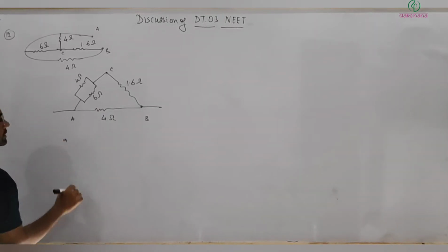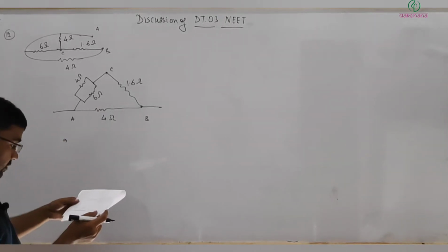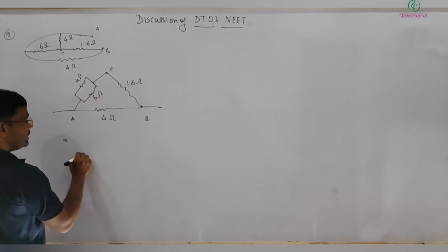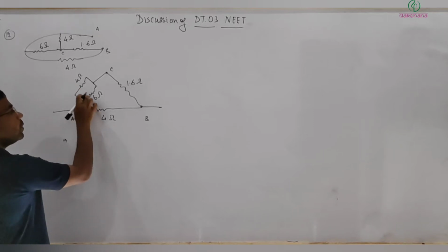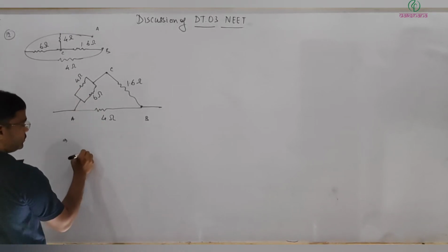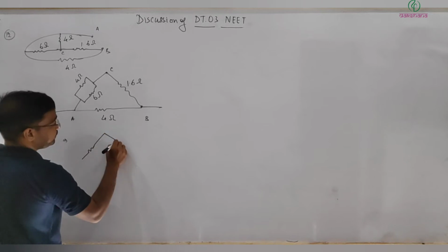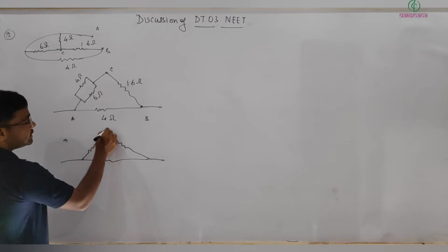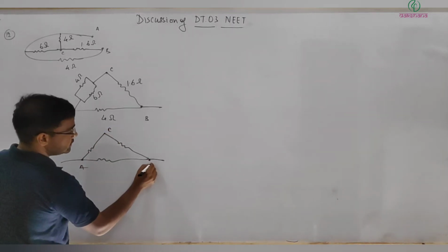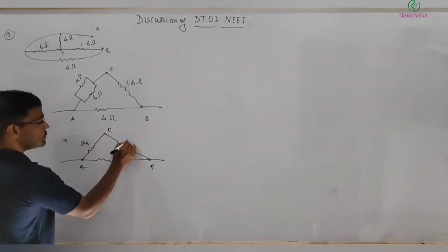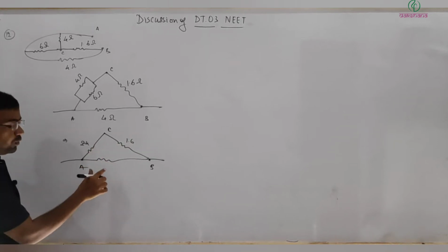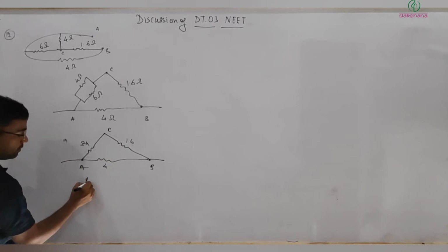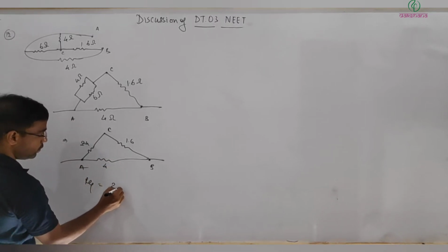So now I can write it here actually. So we can now simplify it. All right. So see, these two in parallel, then the circuit will be what? 4 and 6 in parallel, it will be like 2.4. So this is C, this is A, this is B, so this is 2.4, this is 1.6, and these two will be 4 and this is 4, so 4 and 4 in parallel, so R equivalent between AB will be 2 ohm.